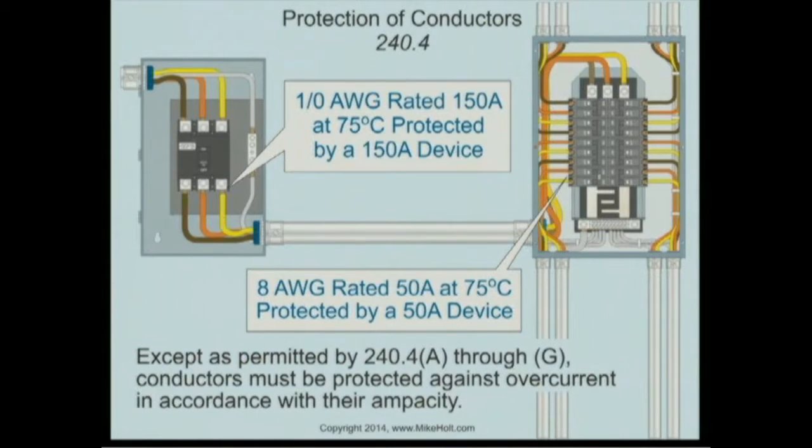So I need to make sure that I look at the graphic and the text, and that I specifically say that the terminals are rated for 75 degrees C. That's a fact for me to size the conductor to 75 degrees C. If not, and I have to be careful in all my examples, graphics and text, I cannot size the wire at 75 degrees C under 100 amps unless I qualify it in the statement.